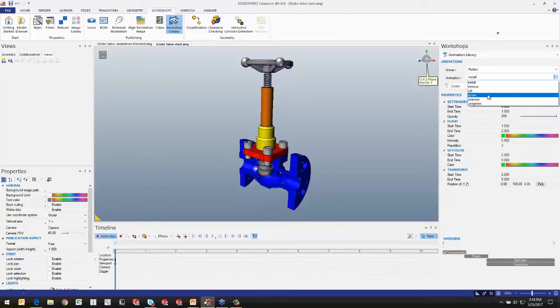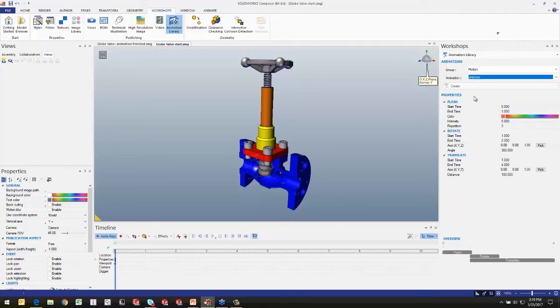So what all things can we do here? A lot of times if we wanted to remove a bolt, when I did it earlier, I just grabbed them and pulled them, stripped out the threads nicely, but we may want to actually have them spin and rotate as we unscrew them. So maybe we'll use the unscrew option. There's kind of an overview down here at the bottom. It's going to flash for a little bit, rotate, and translate. So it's only going to rotate for a little bit, and once it gets unthreaded, then we can pull it straight on out. So the overview there is nice.